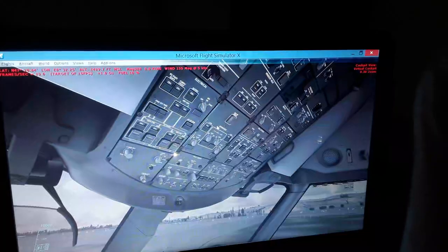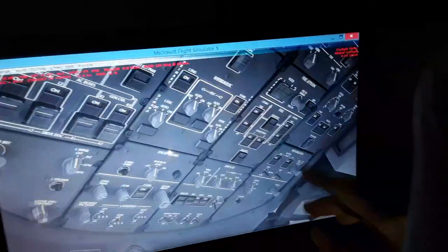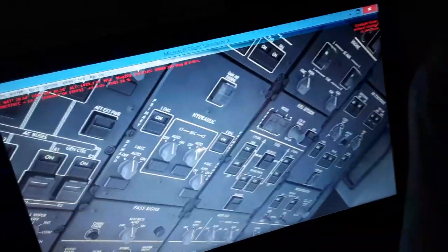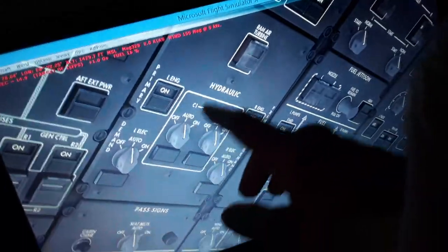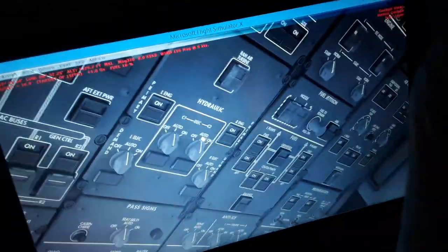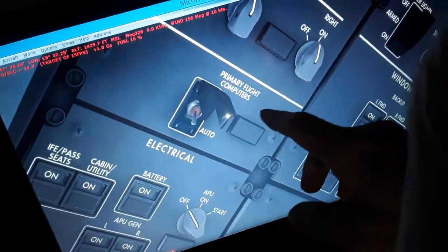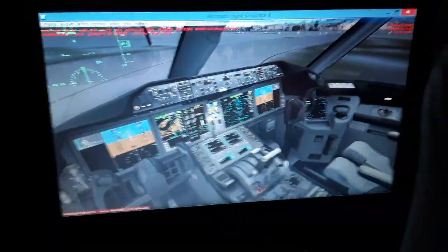So as you can see, we have a failure of the hydraulic systems, pumps, engine driving or electric driving, which are also air pressurized. That will degrade the primary flight control computers from normal to alternate or direct mode. We're going to have a failure of the auto trim functions, and this is a fly-by-wire aircraft. It has the flight control computers. It can also trim itself in flight, trim automatically, the auto trim. We also have the manual trim. We can apply the manual trim with the switches, as I'm going to show you now.